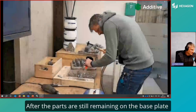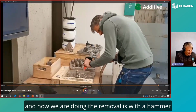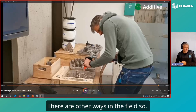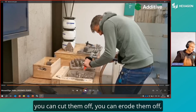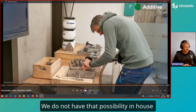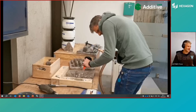The parts are still remaining on the base plate, and how we are doing the removal is with a hammer and with a gouge to remove the parts from the base plate. There are other ways in the field, so you can cut them off, you can erode them off, you can mill them off, or whatsoever. We do not have those possibilities in-house, so that's the reason why we are doing it by hand.